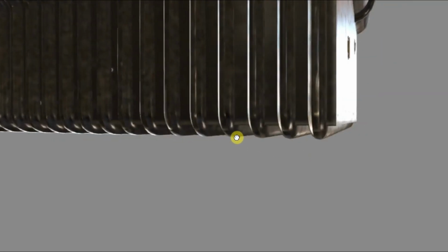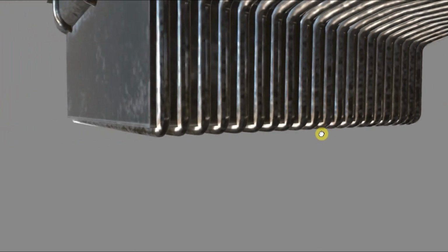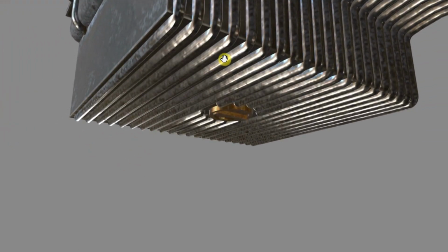Obviously, if we slow the engine down, it means we're not travelling as fast anymore in our van, which means we're not getting as much air passing over these cooling fins. But that makes sense because we're not normally going to sit and rev the engine for half an hour and not actually move the vehicle. So when the engine is working harder, there's more air passing over the oil pan and cooling down the oil. And when the engine is not working as hard, there is less air passing over the oil pan and cooling the oil. But then the oil is not as hot because the engine's not working as hard. So it's almost like a proportional response. The faster and harder the engine works, the more the vehicle is going to move and the more air that can be used to cool down the oil within the oil pan.